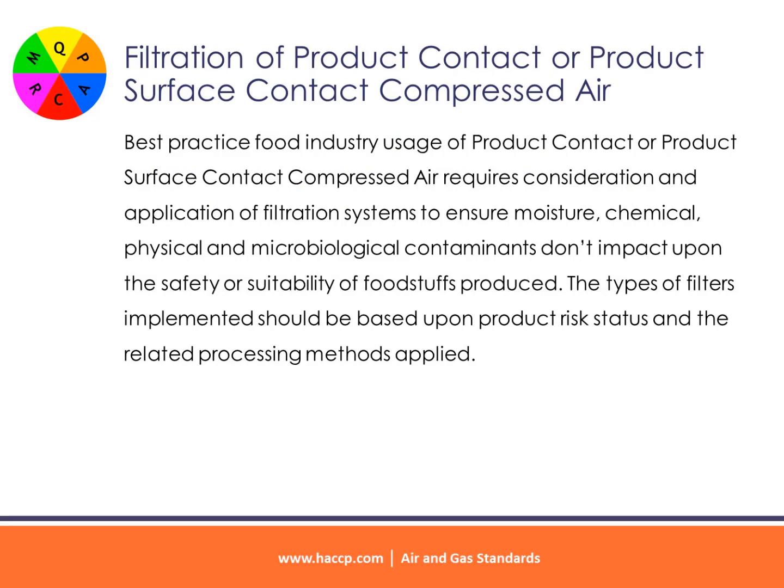Filtration of product contact or product surface contact compressed air. Best practice food industry usage of product contact or product surface contact compressed air requires consideration and application of filtration systems to ensure moisture, chemical, physical and microbiological contaminants don't impact upon the safety or suitability of foodstuffs produced. The types of filters implemented should be based upon product risk status and the related processing methods applied.